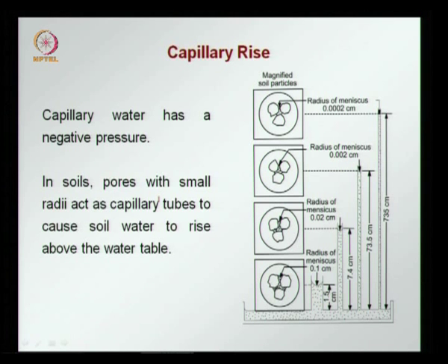Capillary rise is also important in soil. As we saw, capillary rise gives rise to a negative pressure, that is, there is a suction developed. We see here in this diagram that when we have a capillary rise, there is a pulling up of water, which we saw earlier in the case of a capillary tube, and when the pores in the soil are finer, that is, the particles are finer or closer packed, we have smaller capillaries. This gives rise to higher capillary forces and the rise is much higher.